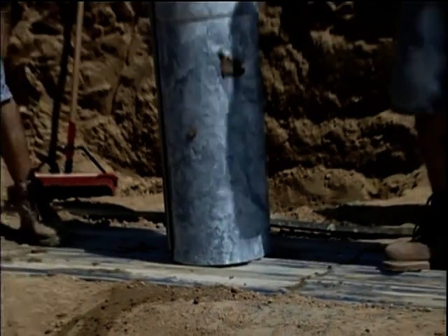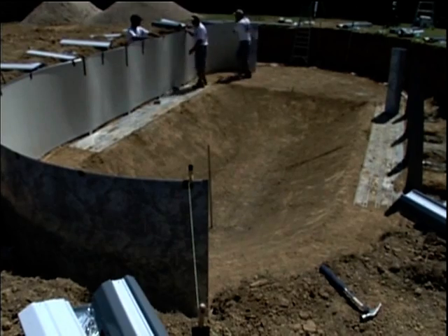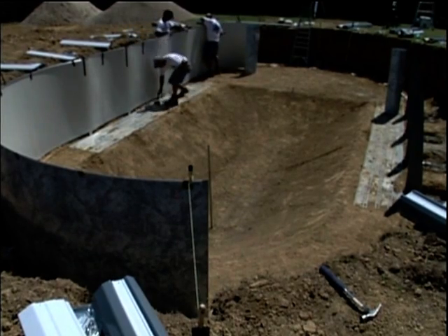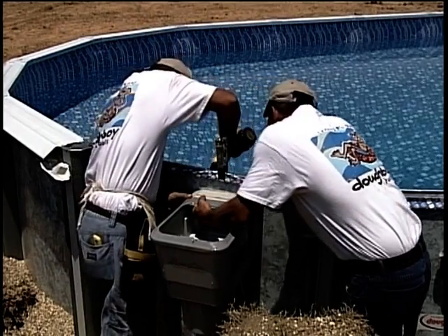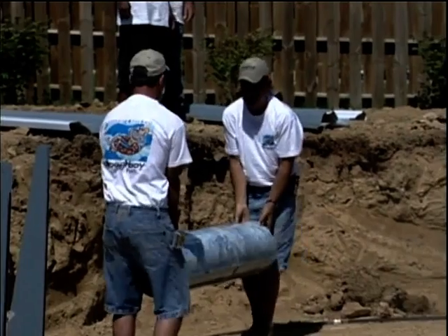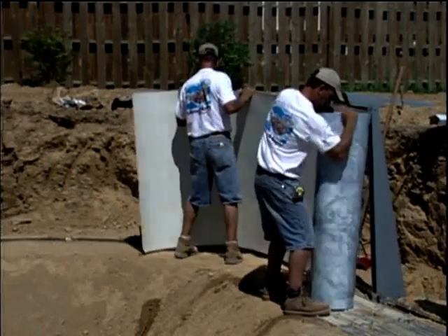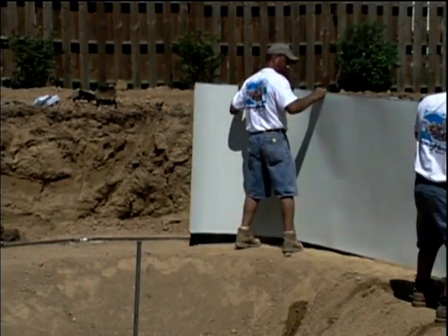Determine the wall starting point from the preliminary planning section in the assembly guide. Keep in mind that the wall starting point will determine where the wall ends and thus the placement of the skimmer and the filter. Also keep in mind that the wall has a top and bottom. There is an arrow label on the wall that indicates the top. Remember that the wall is a coil of metal. Consider using a leather-type glove when handling the wall.